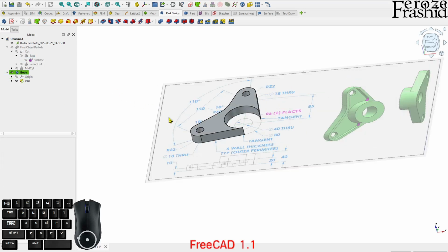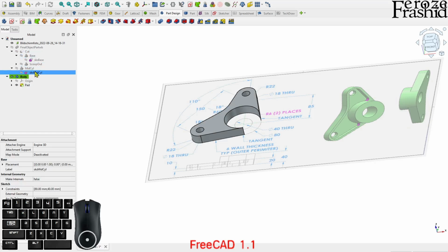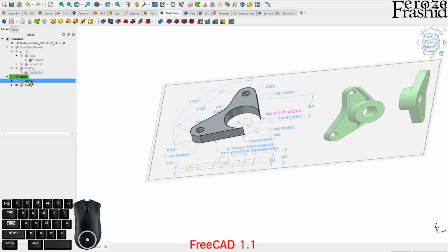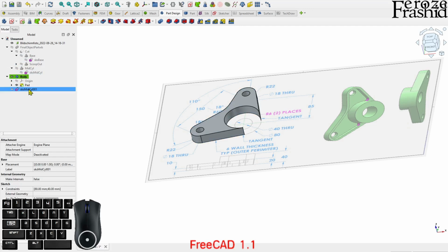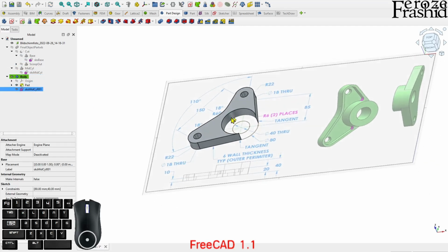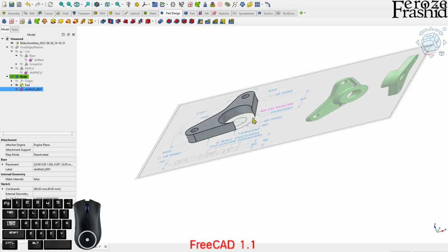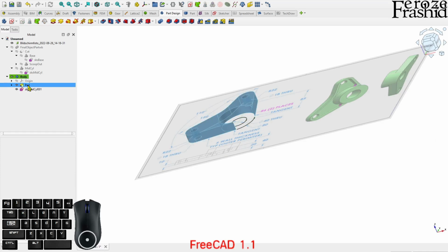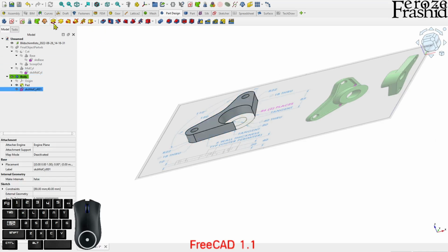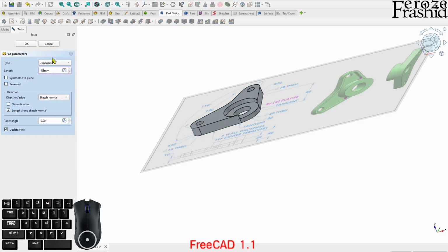And then what we want to do is pull in that cylinder. All right, let's bring this one, copy that and bring it in. Because the body is activated in this tree, I can put it in the body. Let's see, there it is. That's the sketch still at the bottom of the workspace. So now see what happens here. The sketch cylinder one, I can pad it up for 40 millimeter.